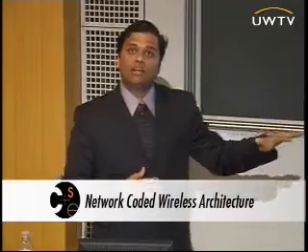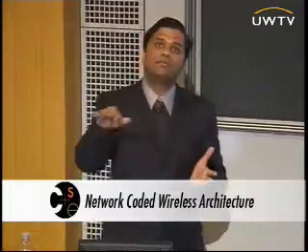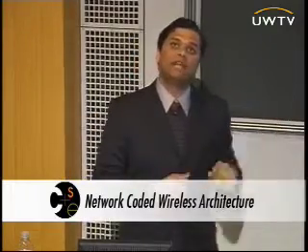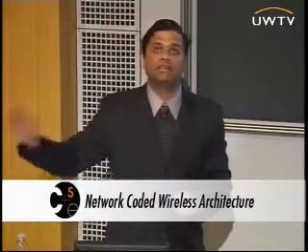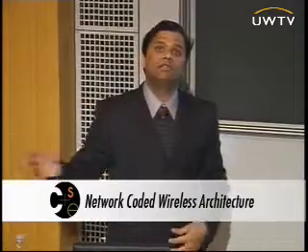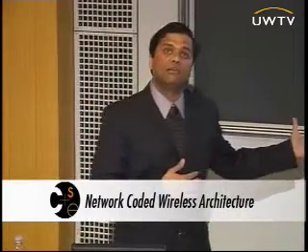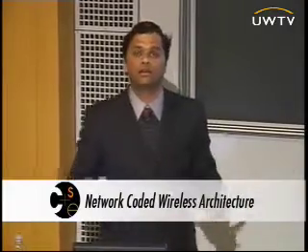There's still work to be done at the network level in getting more throughput out of this network and achieving the same spectral efficiency you would get from an 802.11 access point network. At that point, mesh networks are competitive because they have the same throughput guarantees which an access point network has, and have the benefits of very easy deployment and blanket coverage. And I think at that point, you would see mesh networks out in the wild.